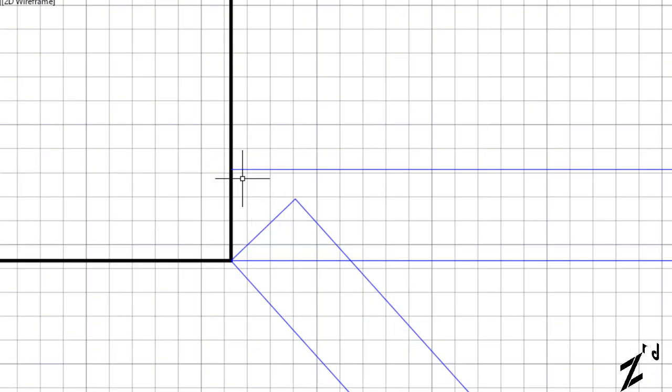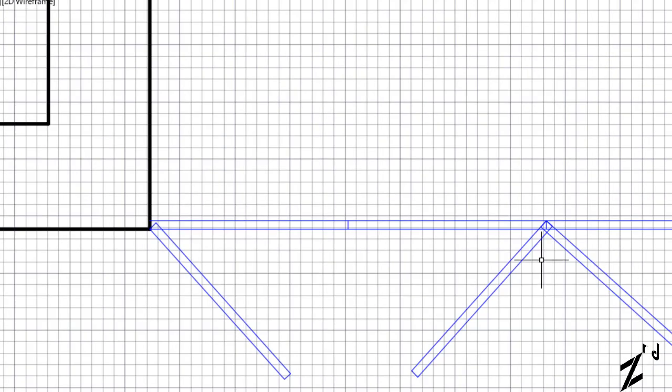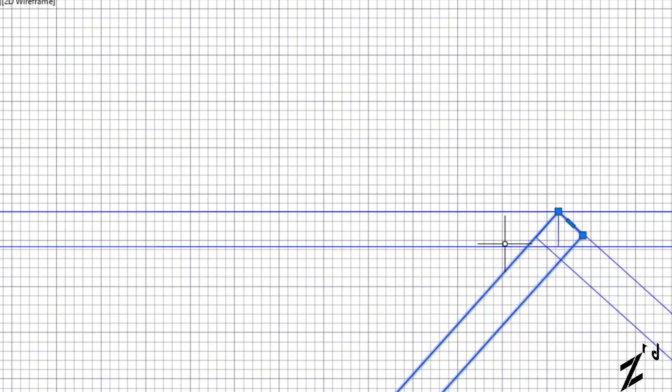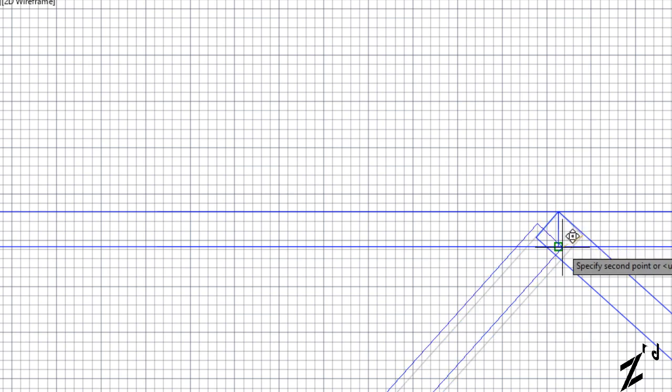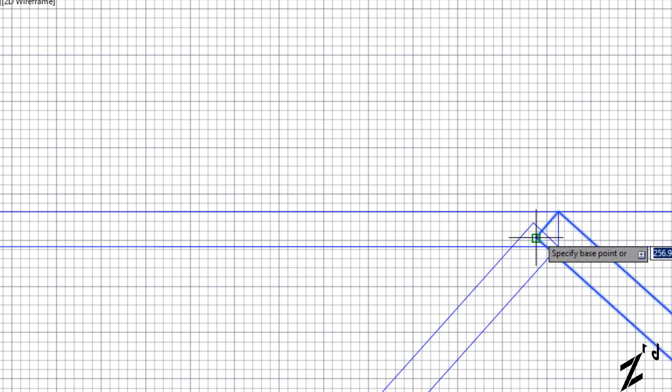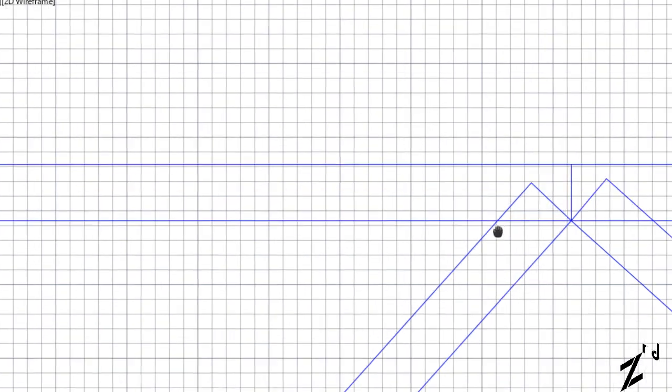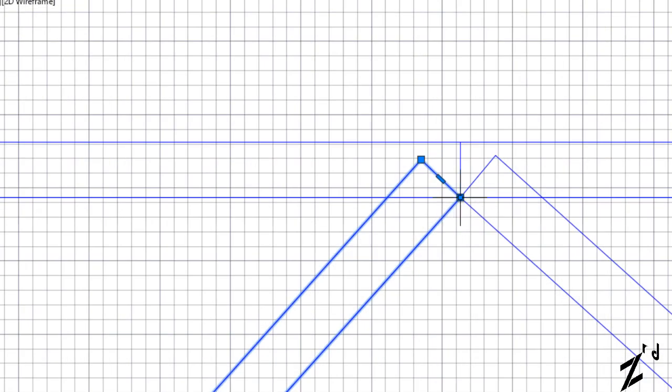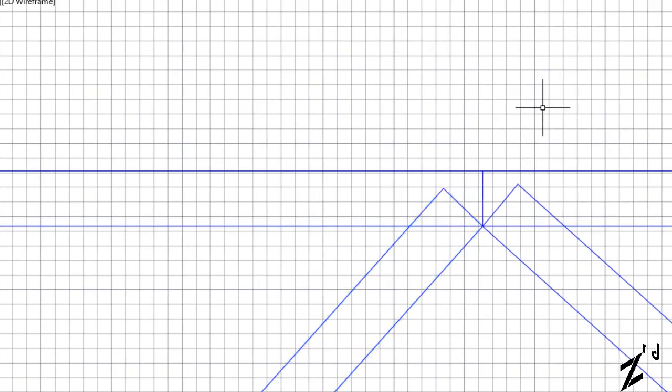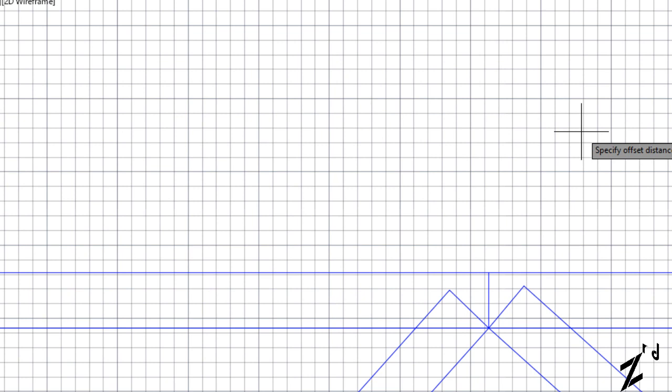So that hinge fits in here perfectly. So this door, there's no issue. This door, on the other hand, has to move. So let's move this here and this here approximately. But still, you need some kind of support, something for these hinges to actually be connected to. And for that, we'll need, let's say, another 19 mm ply along the vertical axis here. So what's 19 divided by 2? 9.5. Let's say 0.95.